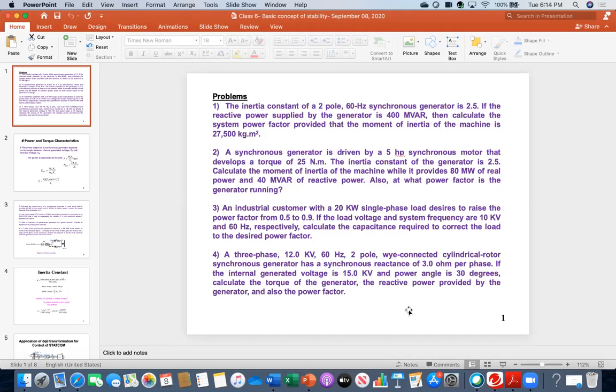Dr. Ali, I got torque value 1.52 mega Newton. Is this right? Mega Newton? No, it should be 0.0798 because Manoj calculated, like he said, 79.8 kilonewton meter. That's correct. I expressed in mega. So maybe you messed up with the radian per second conversion.